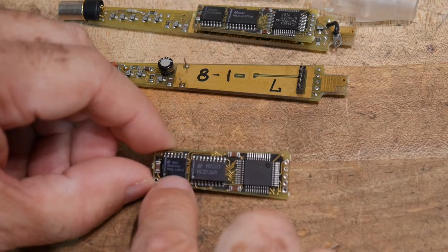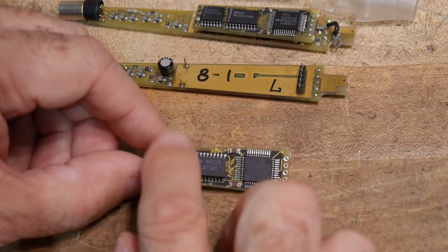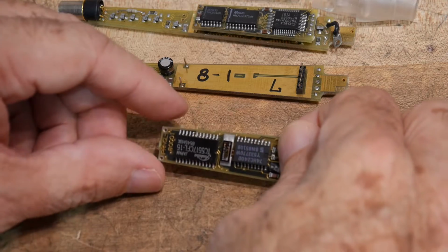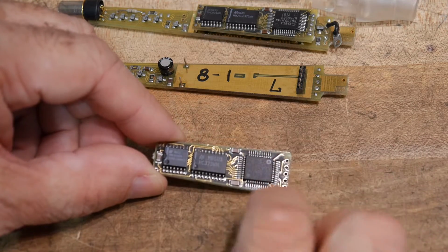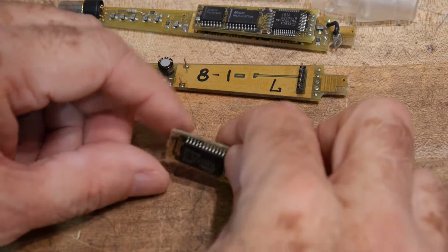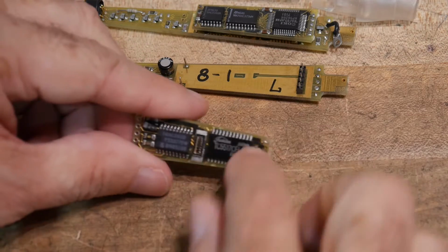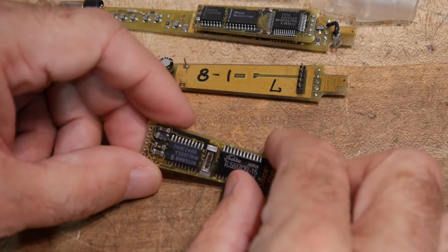This is a 1K EEPROM, so you can store configuration data into a serial E2 PROM. And on the back here we have RAM. There's not enough RAM available in the 8051, so there's, I think, a 2K by 8 RAM chip. It's a Toshiba 5517, a very classic chip.